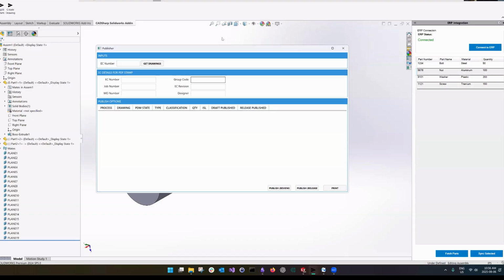Something else we do with these I want to mention is full geometry automation. I don't have a good example to show you here, but if you have a product you develop that's configurable and you need a model for manufacturing for every order, what we'll do is we'll give you an interface here where you pick all the necessary parameters. Let's say a tank. So you pick diameter, height, gaps between panels, nozzles, how you treat the top, how you treat the bottom, and then it generates the full model.